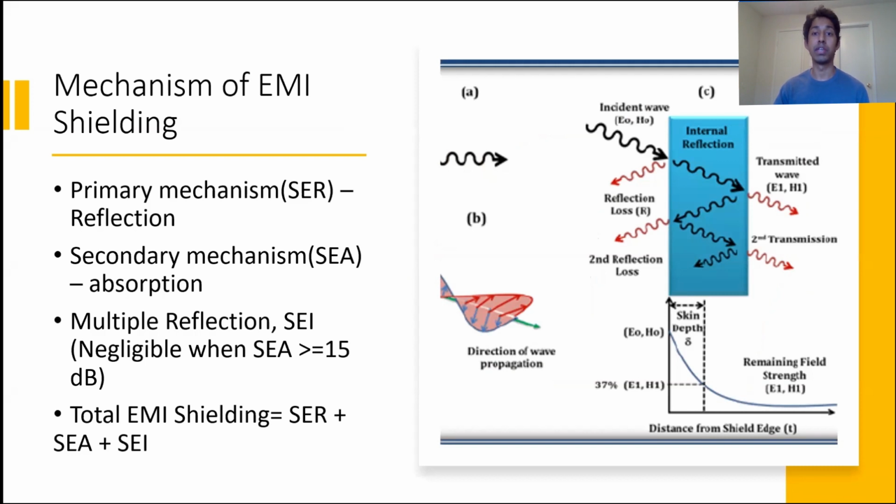The primary mechanism of EMI shielding is usually reflection. For reflection of the radiation, the shield must have mobile charge carriers, for example, electrons or holes, which interact with the electromagnetic fields in the radiation. As a result, the shield tends to be electrically conducting, although a high conductivity is not required. Mainly, when the shielding material is metallic, it possesses free electrons to contribute to the reflection mechanism. In this case, the EM wave reflects back from the surface of the material.